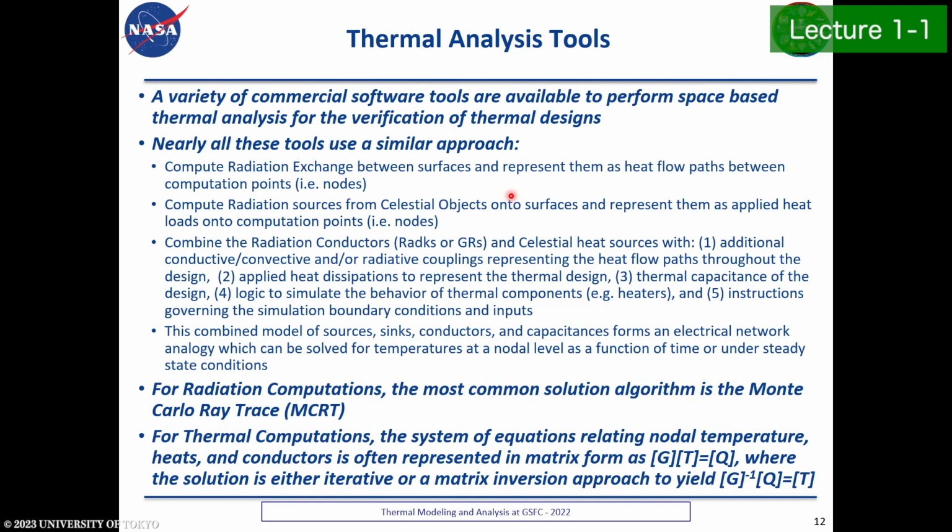So, thermal tool overview. There are a variety of tools available to perform space-based thermal analysis. But they all do things very similarly. They compute radiation exchange between surfaces. They compute the loading from celestial sources such as the sun or albedo or Earth loading or lunar loading onto surfaces. Those feed into a thermal model along with any conductive couplings you may have, additional radiative couplings you may have